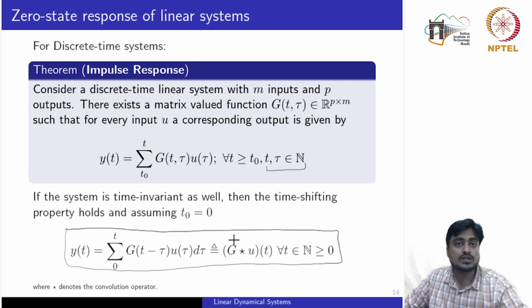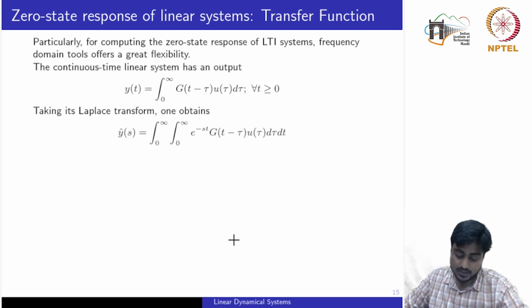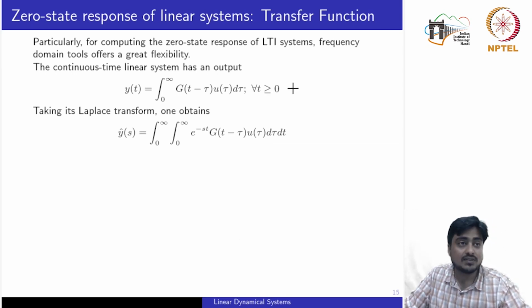Here we see two equations for computing the output of the system in the continuous time domain and the discrete time domain. In both representations, we need to solve either the summation or the integral, which might be a bit time consuming. So in order to obtain the response of the system, we deal in the frequency domain. Let's see the equivalence between the time domain representation and the frequency domain representation. Let's take the first equation, which is the basic equation from the previous result. Now if I take the Laplace transform of this part, we denote it y hat of s.